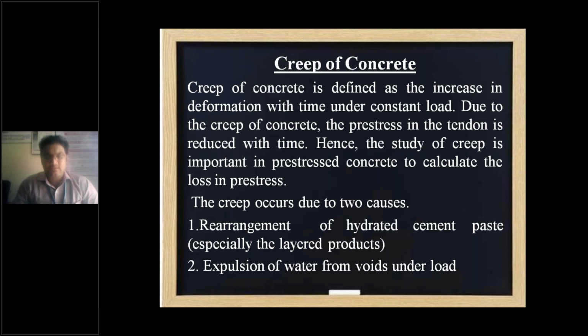Whenever a member is subjected to load, when there is an expulsion of water from voids, then also creep may occur. Okay, creep occurs due to that reason also. So these are the two important things where creep plays a vital role in hardened concrete. You need to keep that in mind. When you are designing, obviously when you go for high grade concretes, undoubtedly the creep and shrinkage of concrete will get reduced. That's the reason why we use high grade concretes in terms of creep and shrinkage also.